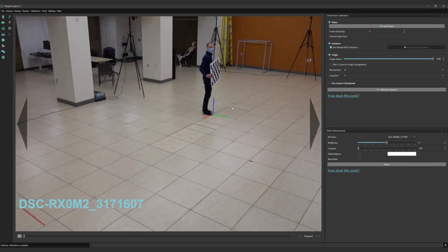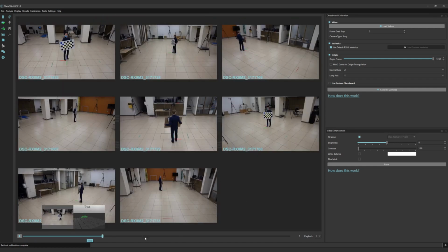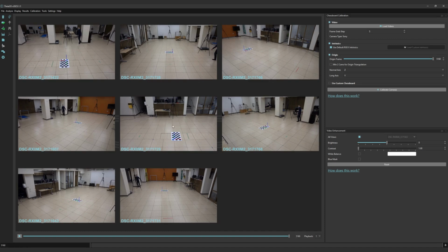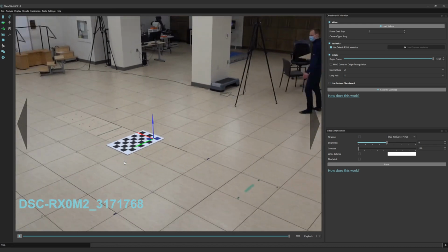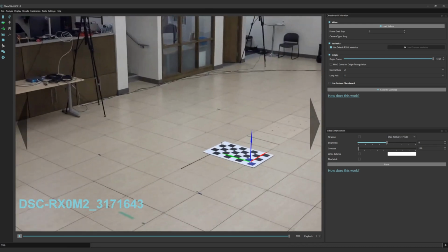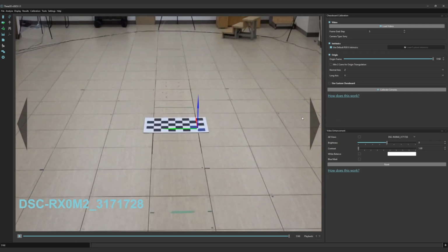It can be useful to place marks on the ground or align the chessboard with existing marks during the localization portion of the calibration trial, which can be used at this stage to confirm that the global coordinate system is positioned and oriented as expected. If your origin is not set as desired, you should watch the Adjusting Reference Frames video for approaches to set it as desired. You may also want to review the calibration videos for visual feedback on the calibration trial.